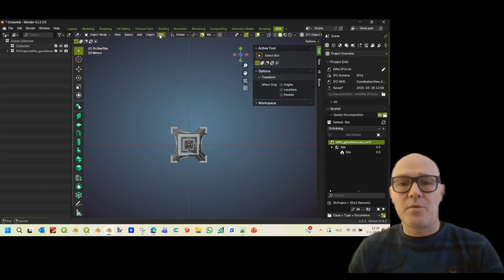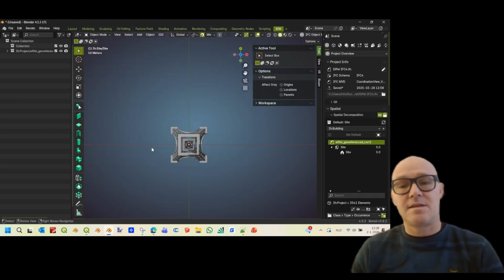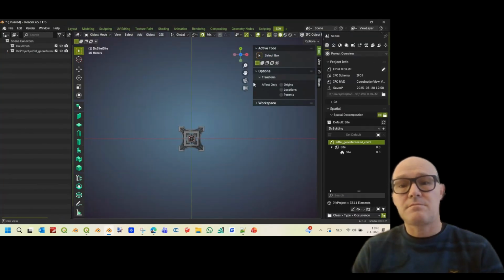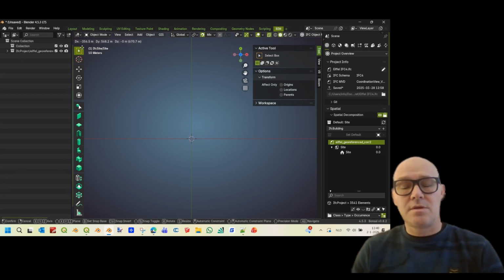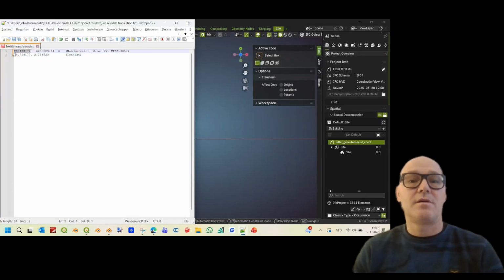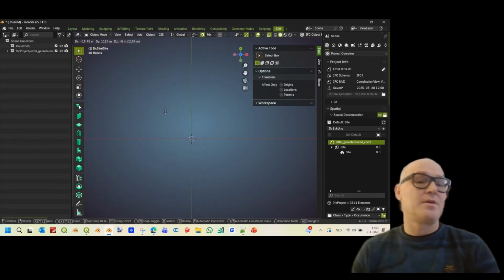Now I want to use this in Blender GIS. This is Blender GIS, an add-on that you can find and install. The first thing I need to do is relocate the model. Everything should be moved from the origin to the XY values, the Pseudo Mercator values.